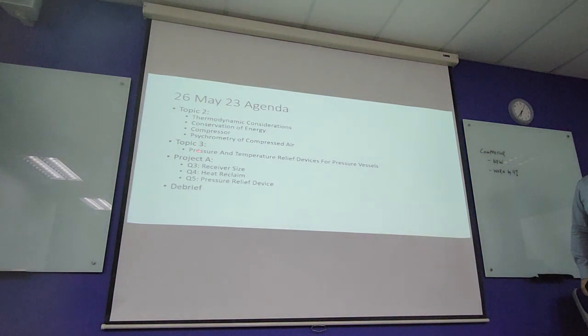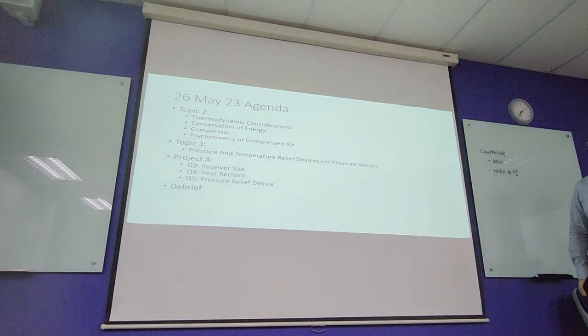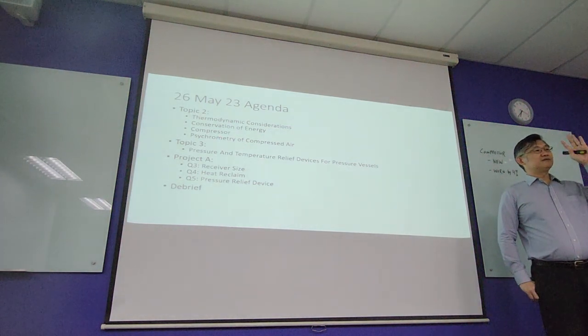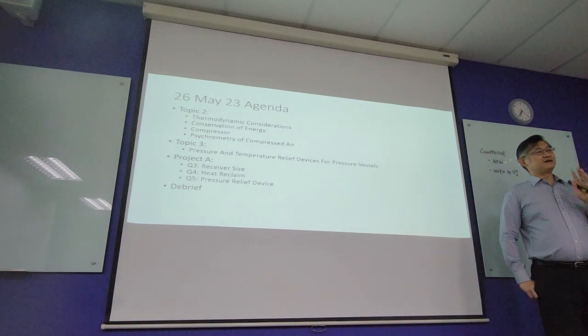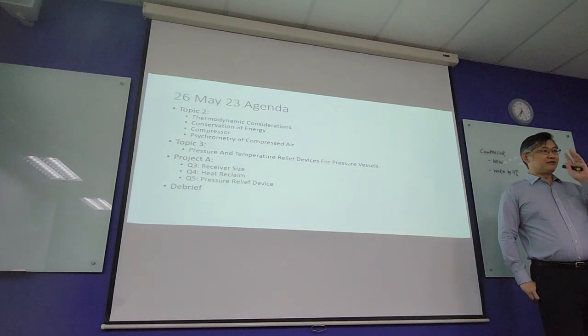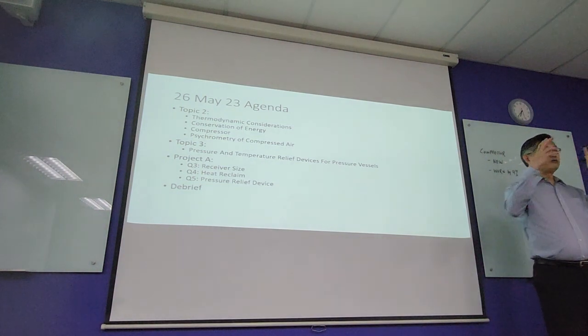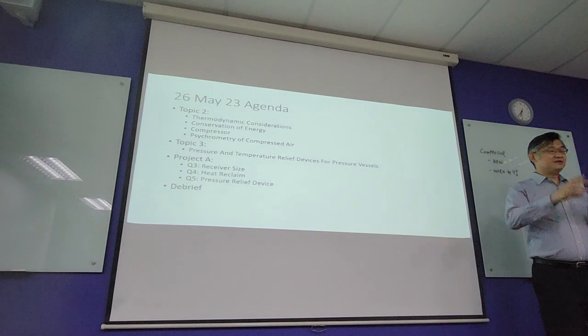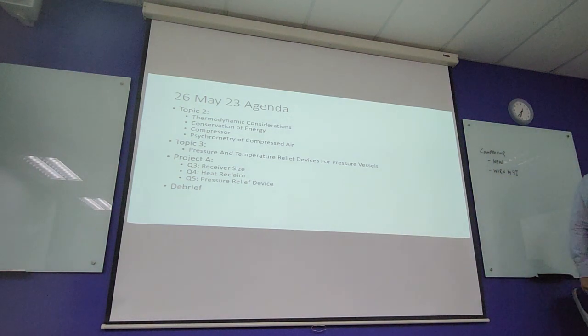We don't want to actually increase temperature during generating of the air pressure, right? Later we will talk about conservation of energy and also compressor. The principle of this compressor as well as psychrometry of compressed air. Mainly we want to filter out the water from your compressed air. So what will be the trouble if we have water inside our air? The steam, right? So we want to avoid this from happening. We want to drain out the water.